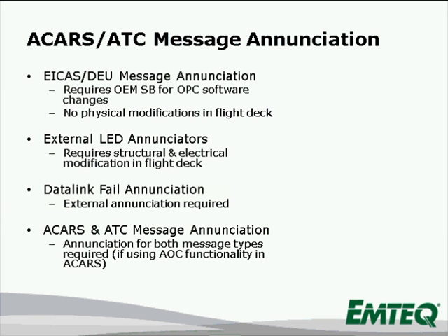As far as Datalink fail enunciation and then the ACARS and ATC message enunciation is concerned, specifically the ACARS, if the operator is not using the system for AOC communications as well, they don't really have to. So CPDLC typically uses an ACARS type system, but it doesn't necessarily have to be used for ACARS. It can be used for ATN and air traffic communications only. But obviously that's very limiting in the fact that it can't be used for airline operational control activities.